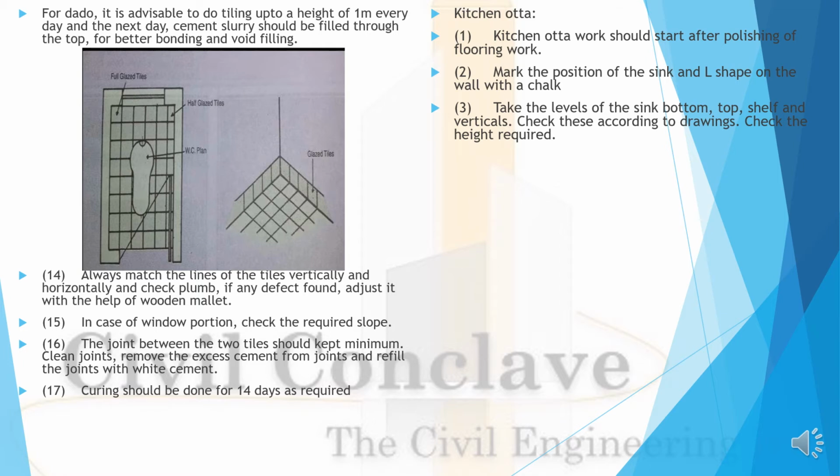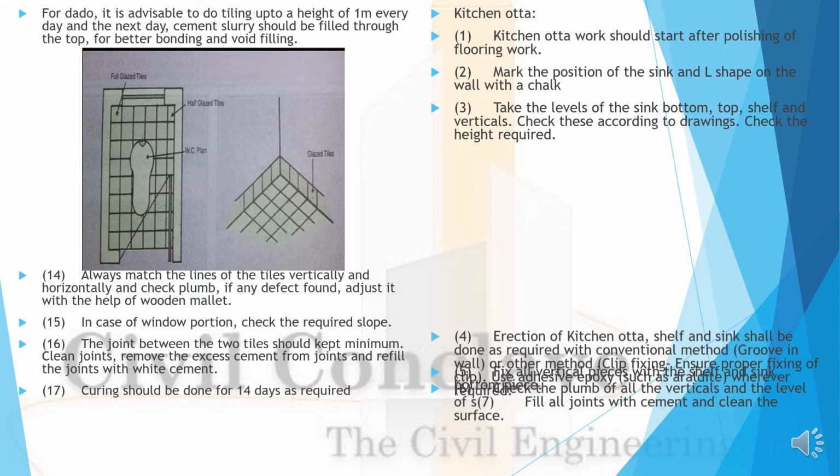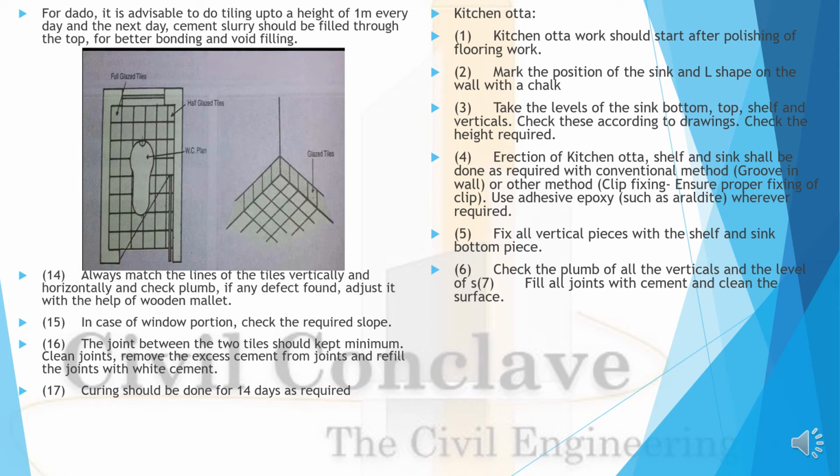Kitchen platform. Kitchen platform work should start after polishing the flooring work. Mark the position of the sink and L shape on the wall with chalk. Take the level of the sink bottom, top, shelf and verticals. Check these according to the drawings. Check the height as required.